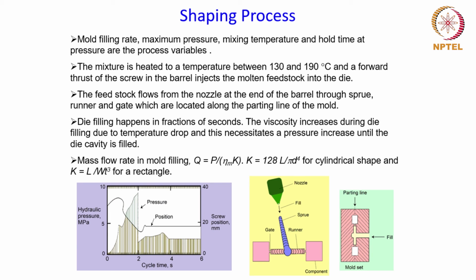And apart from that, the mold filling rate also has an effect on the process, and this rate depends on the pressure. It is proportional to the pressure and inversely proportional to the viscosity of the mixture. So from this you can again see how the entire process of mold filling depends on both the pressure as well as temperature, which controls the viscosity.